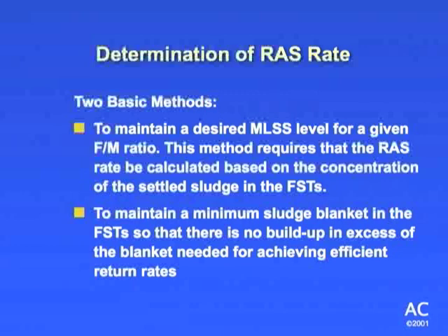Make sure you're keeping your blankets down. I know that this is something that you often have latitude with, but not a lot. We want to try to keep this in the design parameters that have been established for these modes that we're going into, okay? So to maintain a desired mixed liquor suspended solids for a given food to microorganism ratio, that method requires that the RAS rate be calculated based on the concentration of the settled sludge in the final settling tanks. That's one way of doing it.